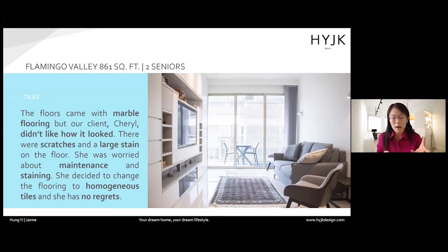With marble, it's a natural material, so it's porous, very easy to stain, and more difficult to maintain. You have to keep sealing the floor. In the end, she decided to change to homogeneous tiles, and she has no regrets. With marble flooring, you need to spend quite a bit of money and time on maintenance. Marble sealing is commonly done every 6 months to a year. So that's quite a hassle each time you have to do it.